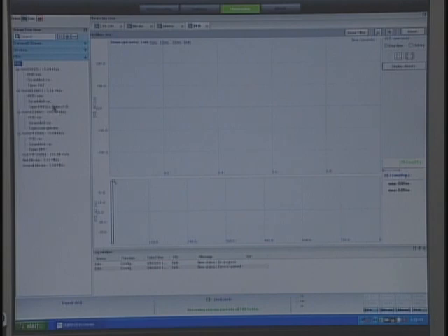And if you want to take a look at one of them, we'll grab the largest one, which is 3.12 megabits. You would grab this one, drag it and drop it in here, and you can start analyzing what's going on. What you see here is jitter. If you move your mouse over it, it highlights the different parts of it, and it tells you what the jitter is. If you move your mouse off the screen, you can see it in real time as it's going along.